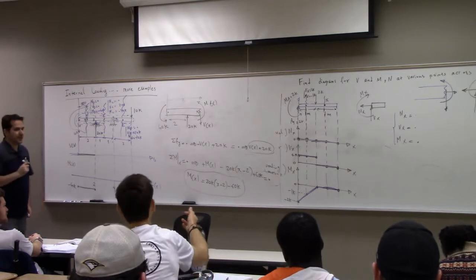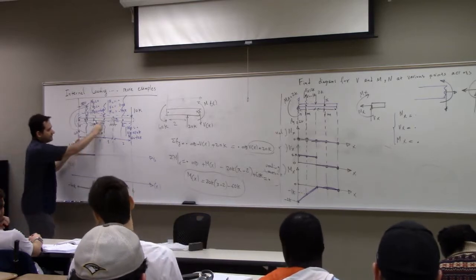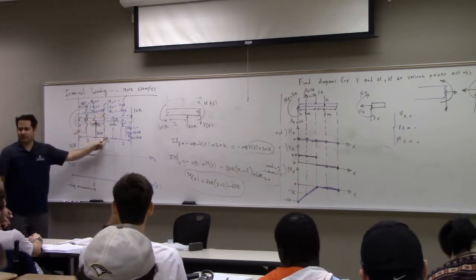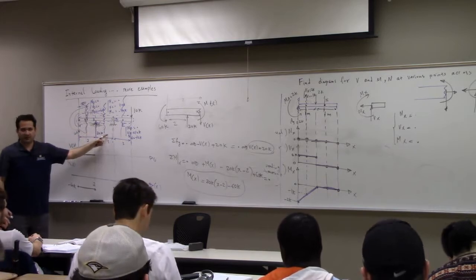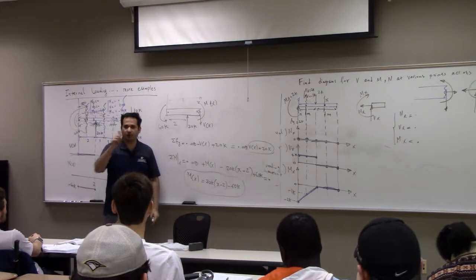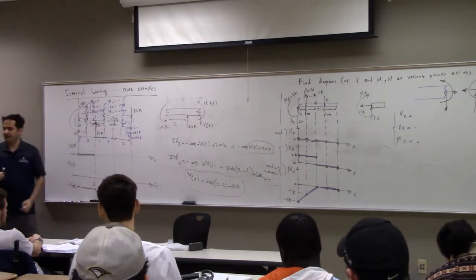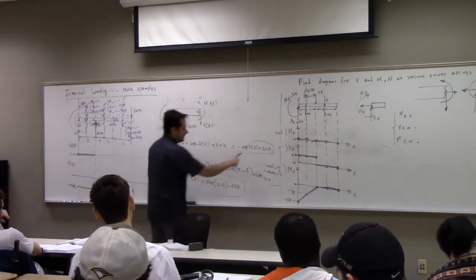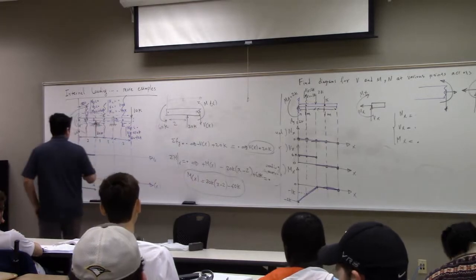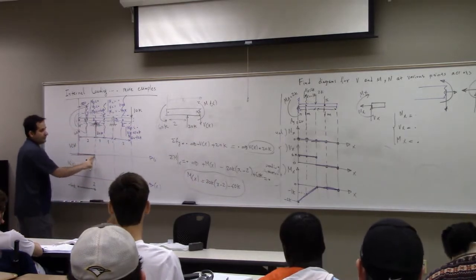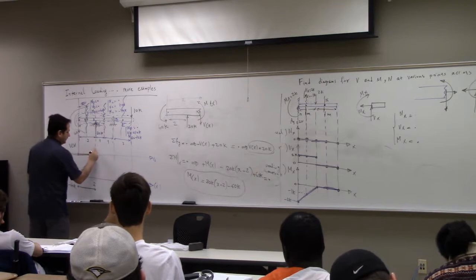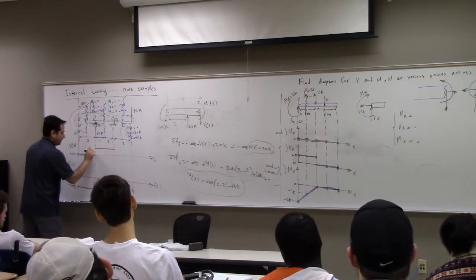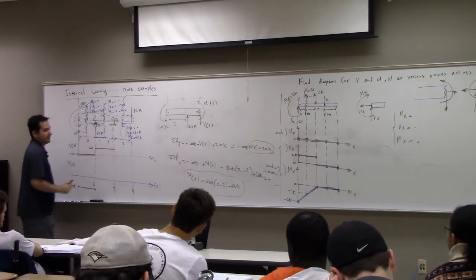Now if I put x is equal to 2 plus 1, 3, then you must retrieve the value that we manually compute only at point C. You see that? But this is more general. This is valid for any point, not only C. So that's the advantage of taking X. So let's draw this. Shear force is 20K. So you have a jump. The shear force was 0 previously, and then you have 20K. So you have some sort of jump. So this is 20K from here to here.